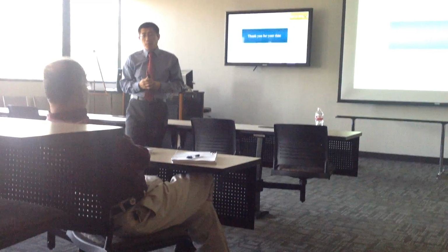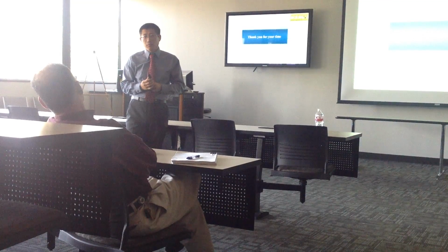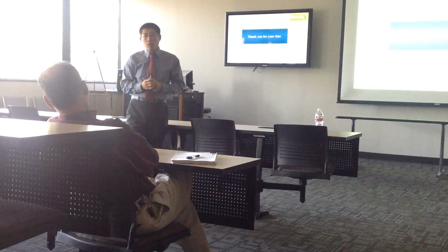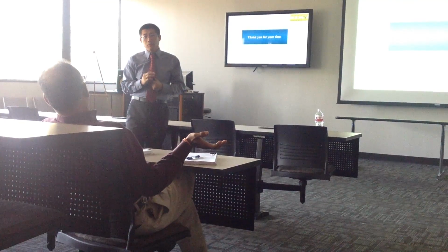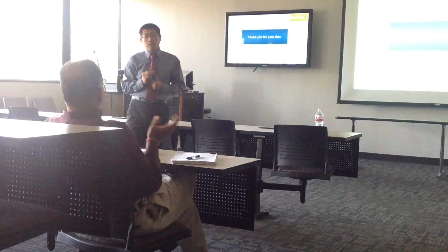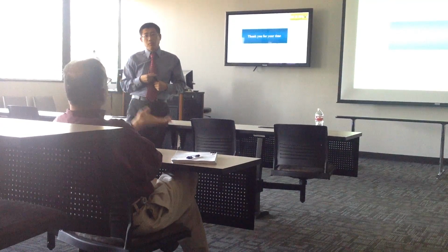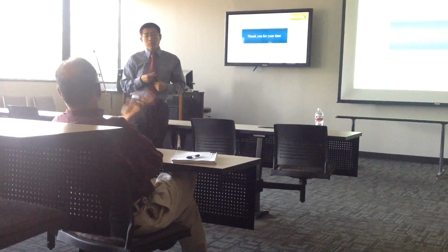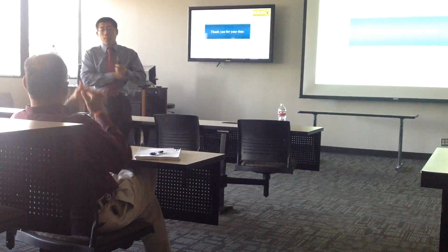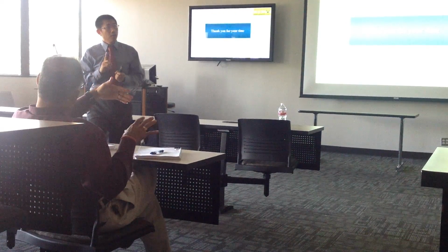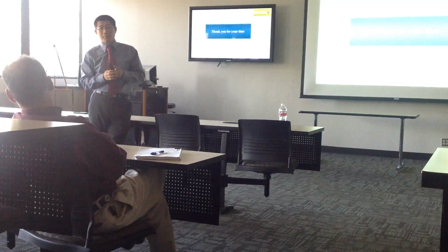Okay. But if from your study you think there is a reason why we should look at a different Y plus value, nobody says otherwise, unless this is a standard and there's nothing that can be done about it. Otherwise, just because five people before you studied and used only a Y plus of 150 doesn't mean we have to stick to the same Y plus, right? Yeah, you can. So if there is a reason, meaning everywhere 150 is off, there may be another point between 30 and 150 that may make more sense.